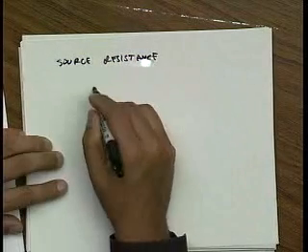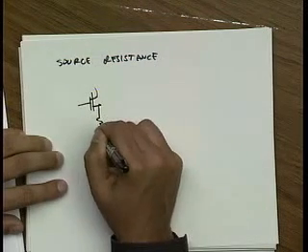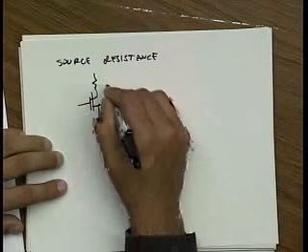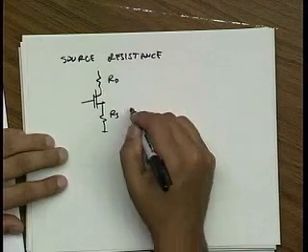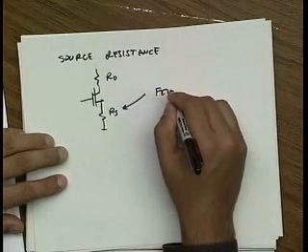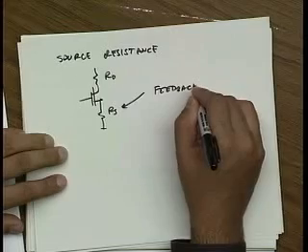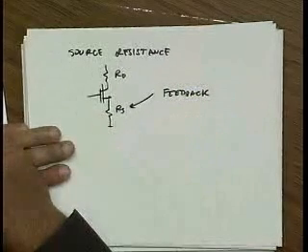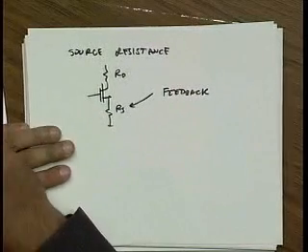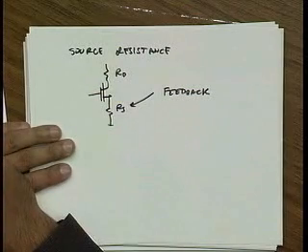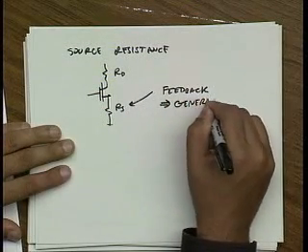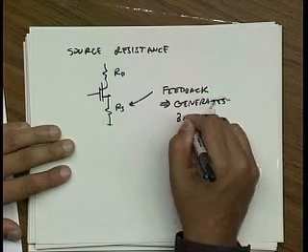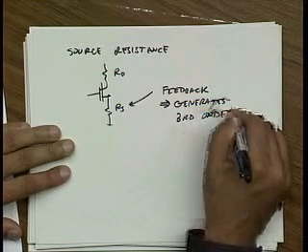So source resistance, if I look at my FET, I always have a source and a drain resistor. And what we'll show next lecture is this is a feedback mechanism. You say feedback is good, right? It should reduce the distortion. It does, but unfortunately it also generates third order. Okay, we'll see that next lecture.